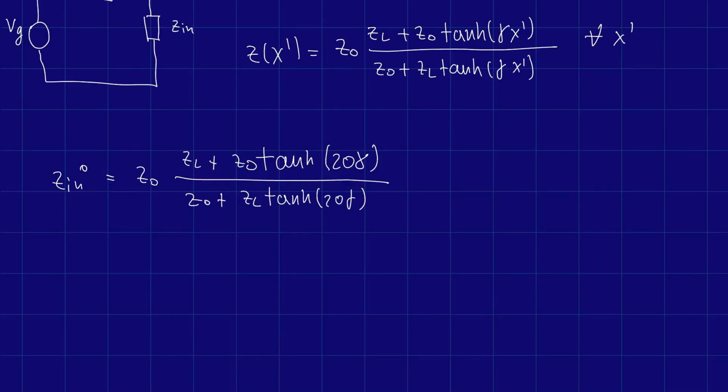Now here notice that for an open circuit, we can just say that the load is infinite ohms. So we can write that this is equal to Z0, and we can take ZL in front of the parenthesis, which will simplify our calculation, and inside we will have left 1 plus this term right here divided by ZL.